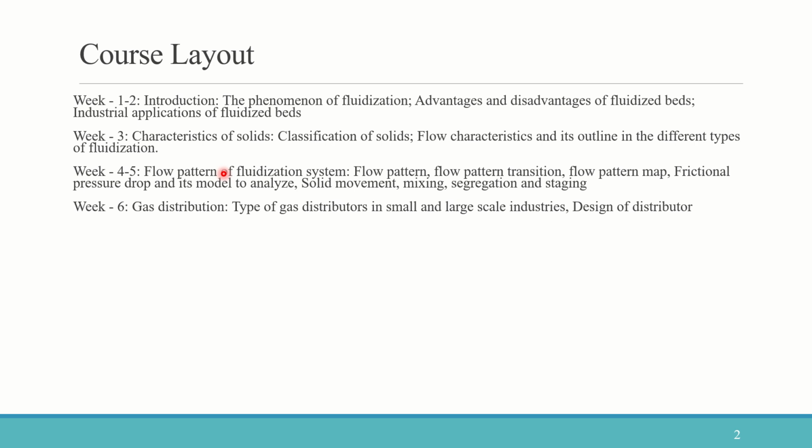types of gas distributors, because in laboratory scale we can use whatever we want, but in industrial scale, at that high level, the main problem would be pressure drop, because it should be under our control, and it should also be economically feasible to use at industrial scale. So that is a major influencing factor when we are talking about scaling. Based on that, we have different types of distributors, and they should produce uniform gas distribution, and the flow pattern should be what we require. So this is gas distributors.